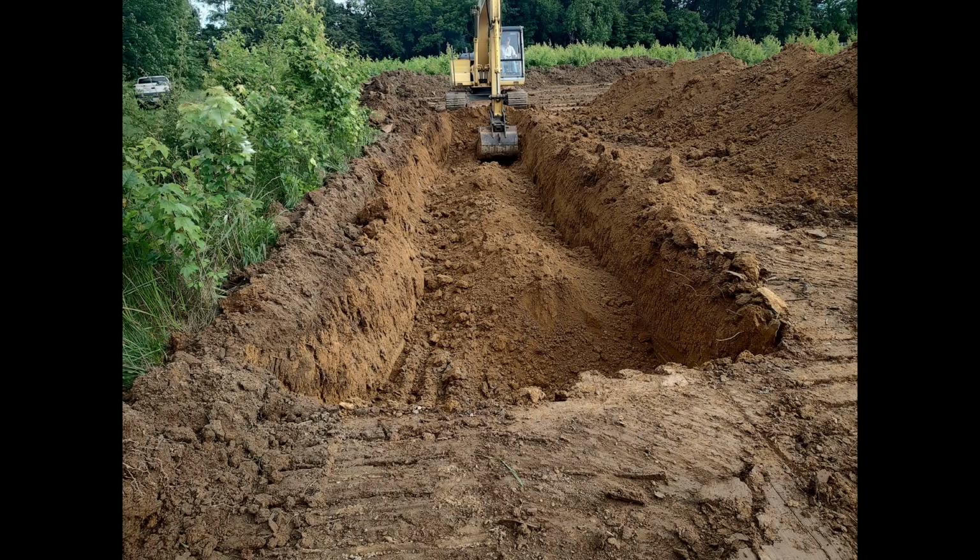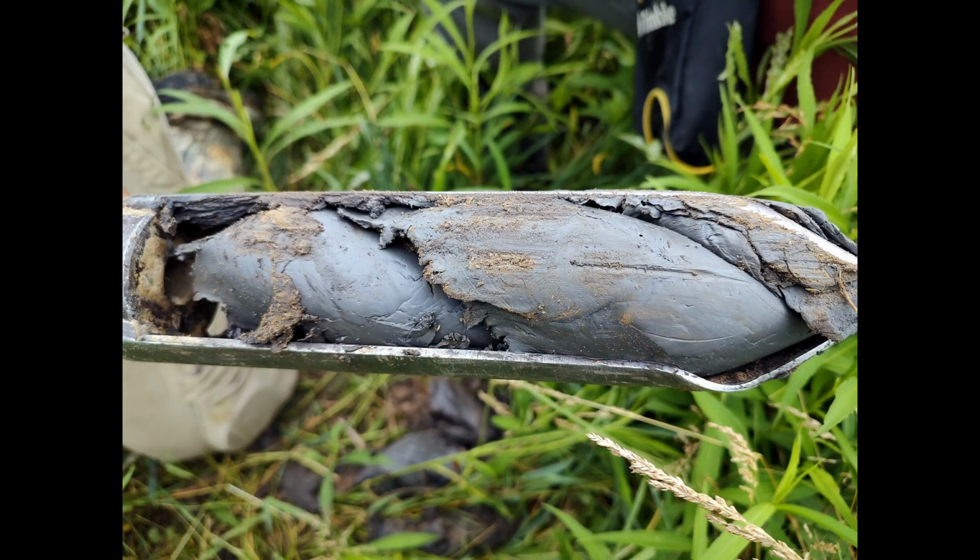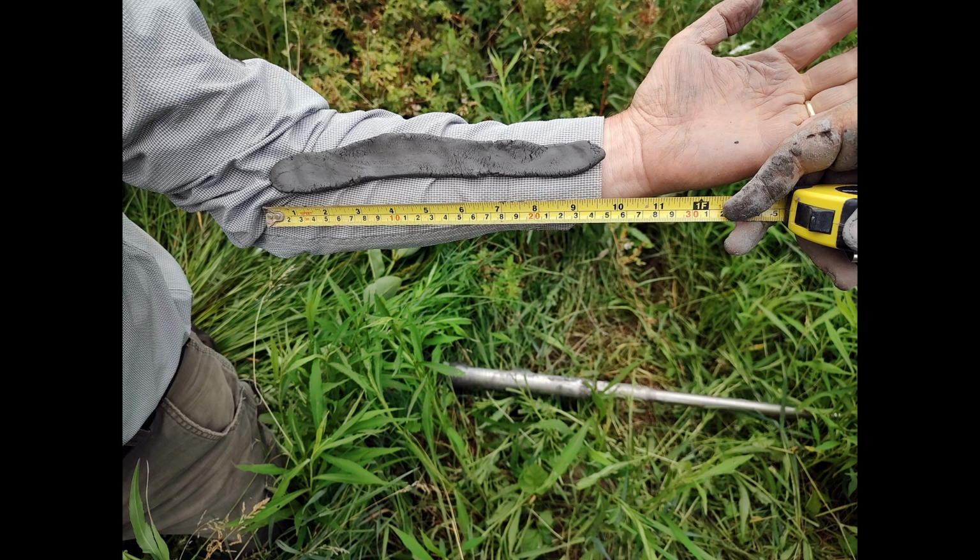It's very important to determine if that deep layer of clay is going to be a good foundation for the groundwater dam. The dense clay you see in the soil auger was brought up from 10.5 feet below the surface. This thick layer of clay would make a great foundation for a groundwater dam. This long and thin ribbon that we formed from the soil in the auger shows that it's very high in clay.